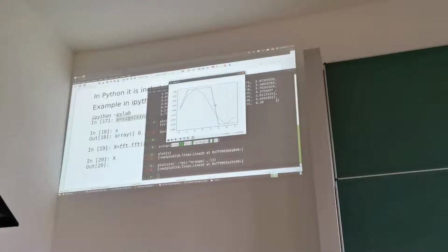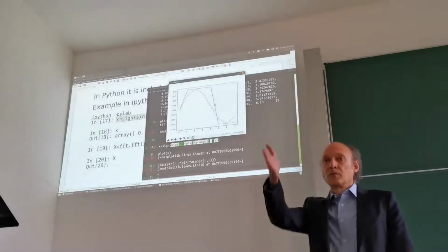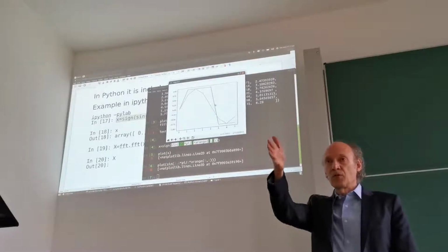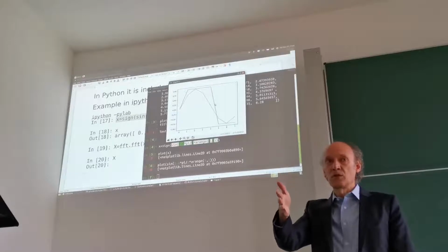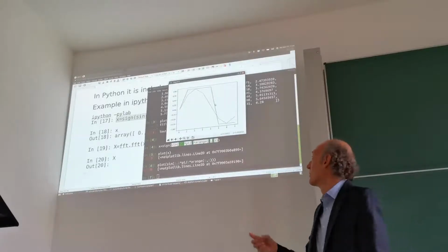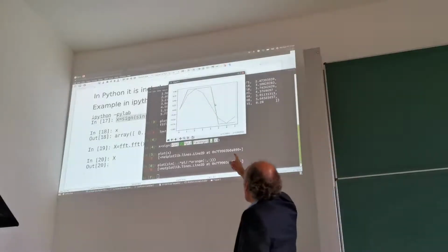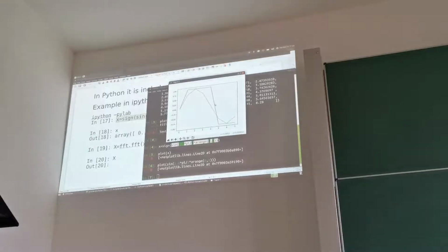And this is actually what introduces high frequencies. This sudden jump means we have a high rate of change, and this high rate of change is characteristic for high frequencies. So now we can see how many high frequencies we have if we apply our DFT to this signal.